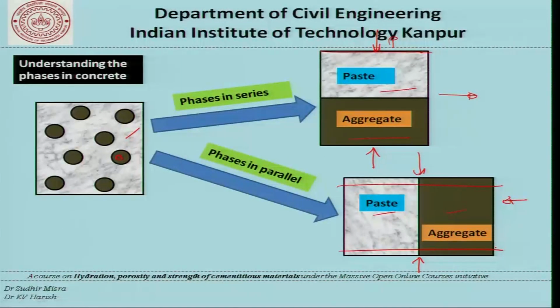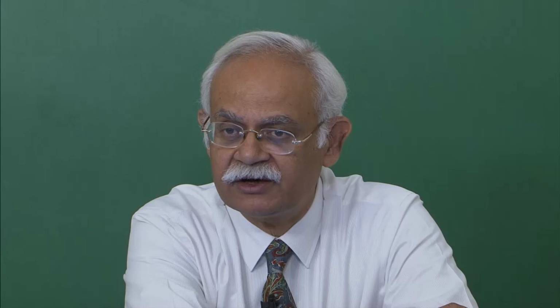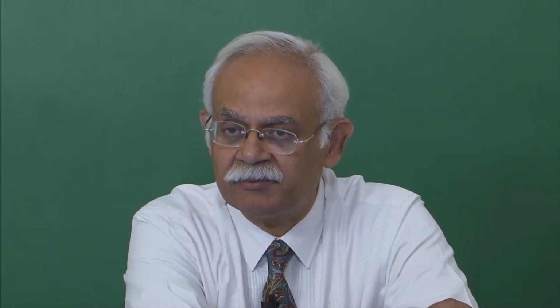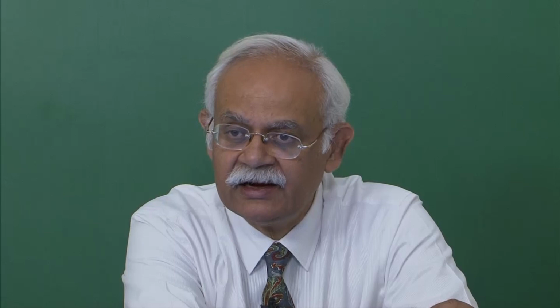And obviously in real life concrete, neither are the aggregates in series nor in parallel, but some kind of a combination. What we need to understand and appreciate is that a model of concrete, or our understanding of concrete, has to be that yes, it is a material which is a composite where one phase and the other phase are different, and at the end they also have an interface.